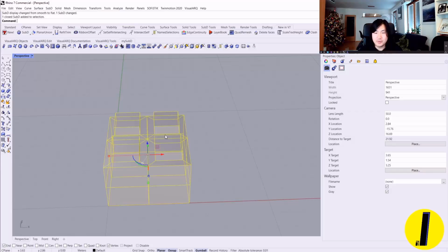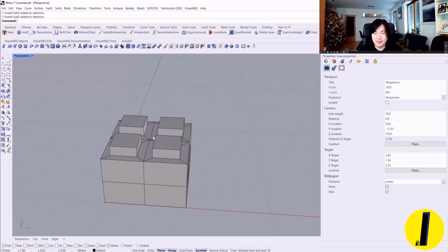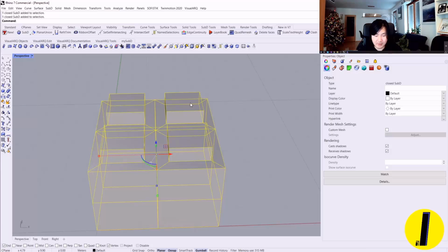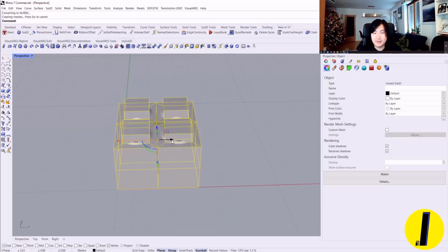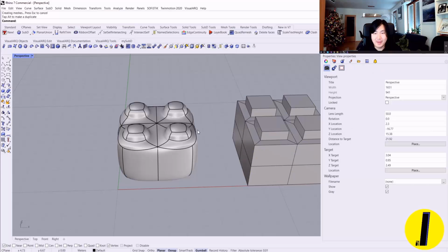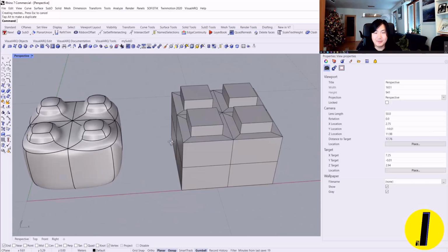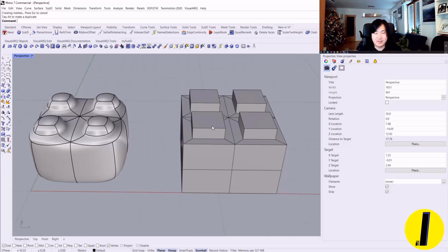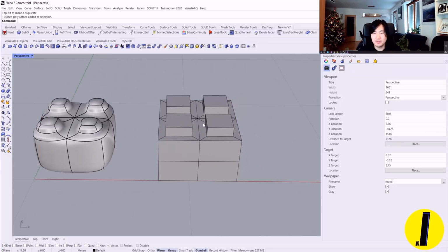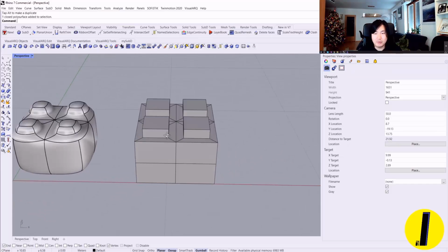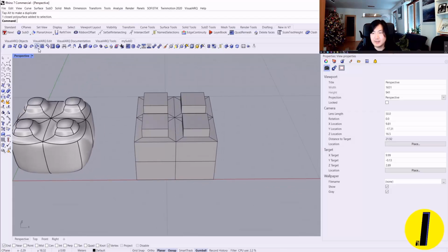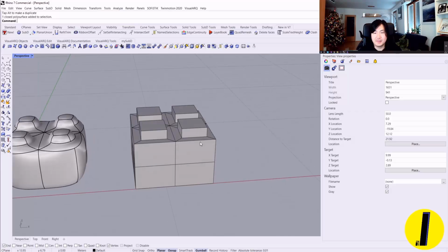And of course this is not yet it. If we convert this to Nurbs, for example, there is a conversion tool here, convert to Nurbs, and if I convert them, as you can see, that's actual Nurbs. So we cannot really convert this box geometry directly to Nurbs, but what you can do is select and add crease on this geometry.